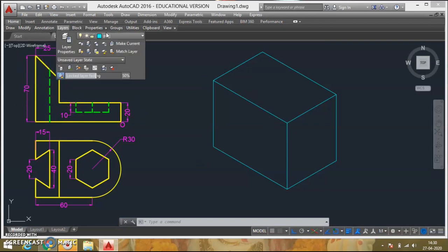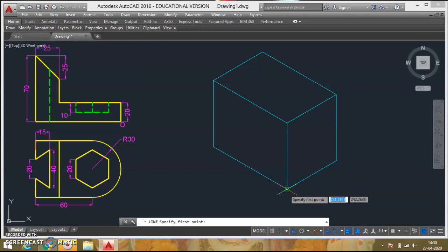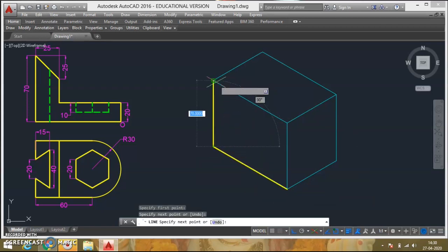I can consider the object layer, that is, I'll draw the dark line, not the complete final line, but a dark line. We'll draw from here, then to this point, these two lines, because this is there and this is there. Then this distance is 20. So I'll draw a vertical line passing through this point for a height of 20.